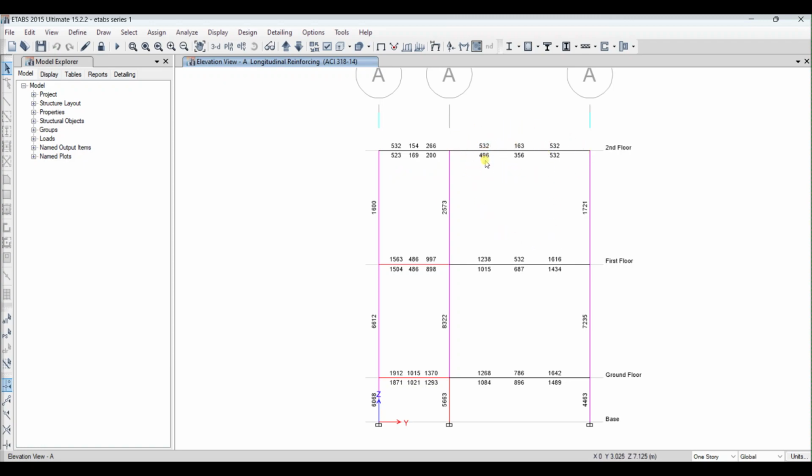So you make the groups of these reinforcements. Some 3 or 4 beam types you can make. You cannot design every element on the base of the ETABS result. You need to make the groups of these results and decide the reinforcement on base of that groups. Okay, which is near, give the near reinforcement after applying the number of bars and size of bar.